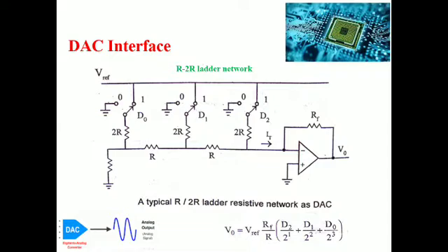The time required for converting the digital signal to the analog signal is called the conversion time. It depends on the response time of the switching transistors and the output amplifier. If the DAC is interfaced to the microprocessor, then the digital data signal should remain at the input of the DAC until the conversion is complete. Hence, to hold the data, a latch is provided at the input of the DAC.